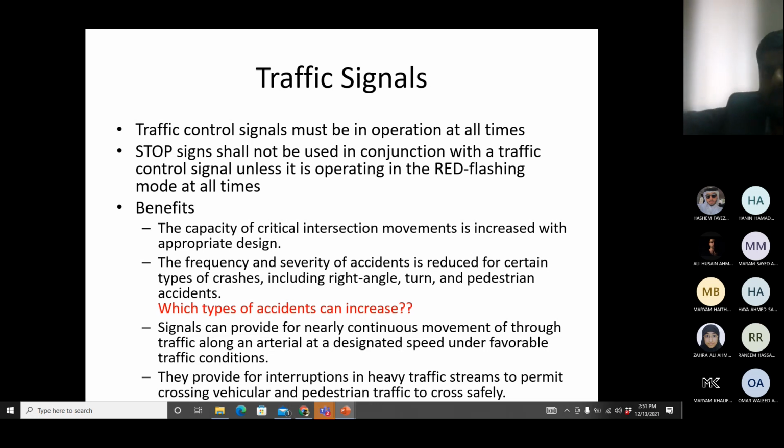Signals on a highway are coordinated so that cars which are on that highway can move continuously through the series of signals. So when they reach the next signal, it is already green for them and they can keep on moving. Okay, so if you come to the signals which are installed on 16 December highway and you are moving straight, the signals are timed according to it, so that you can keep on moving. Not all the cars which are coming from one signal to the other, but some of them. Okay, they can continue moving.